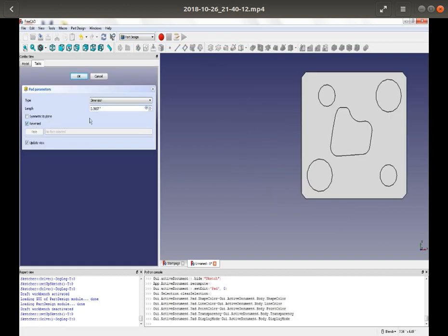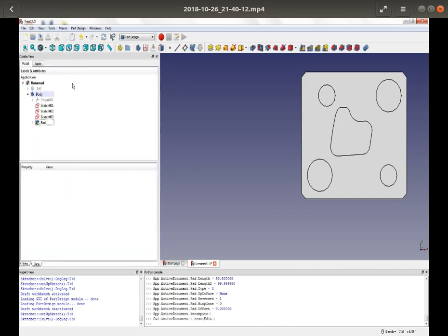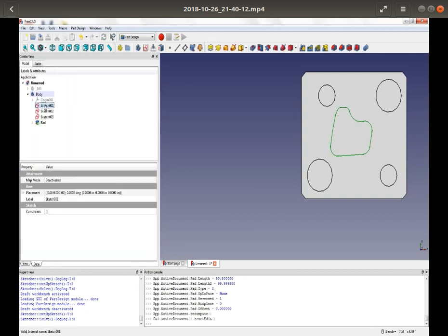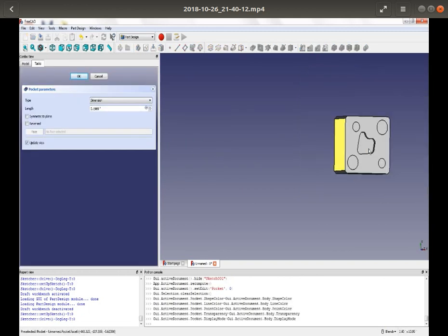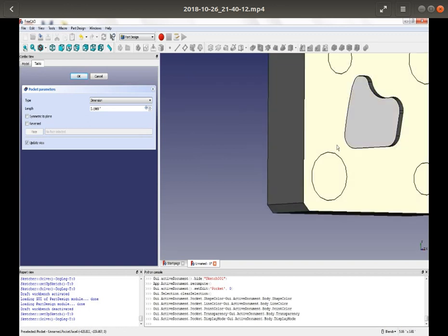So we have our block. I'll reverse it 2 inches. Everything I usually program on my CNCs, top of the part's Z0, so I like to draw that way. Everything's Z negative in my drawings. We're going to use that center one drawing to create a pocket.